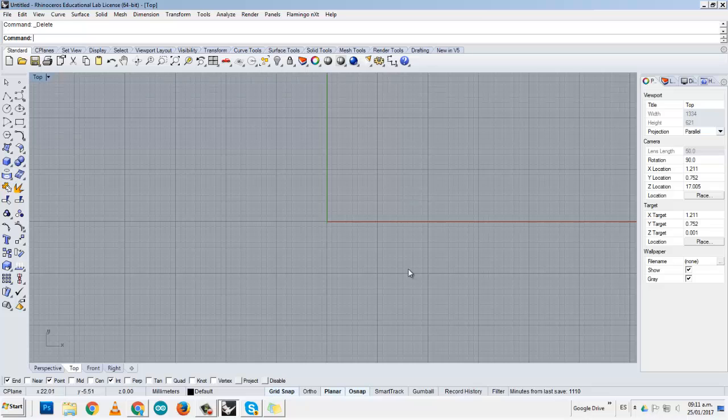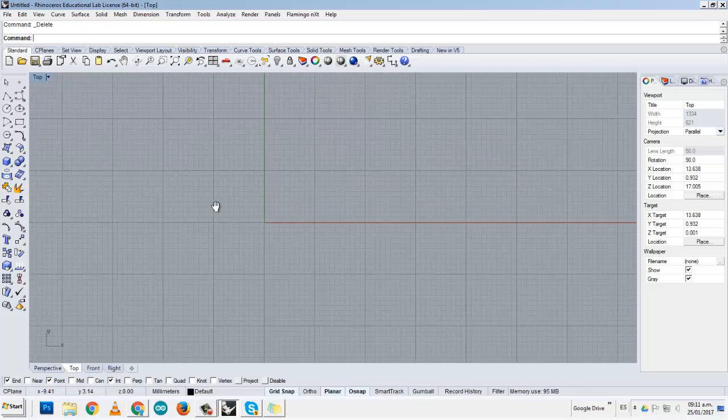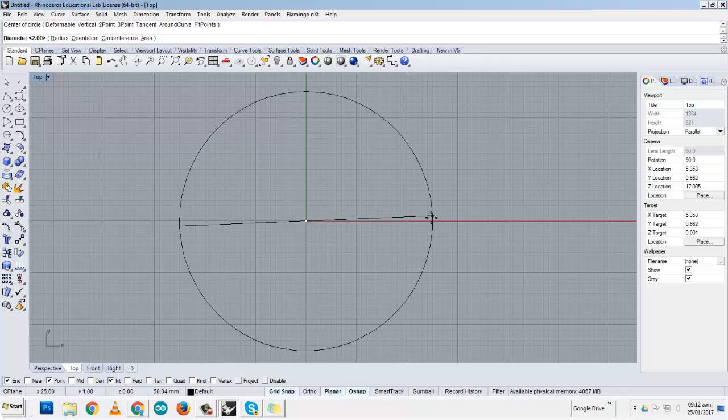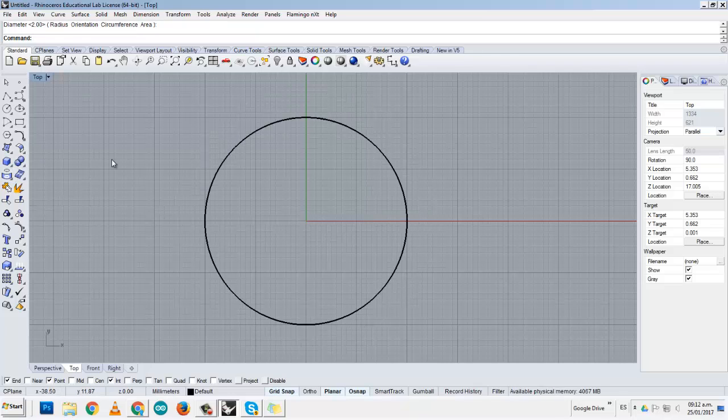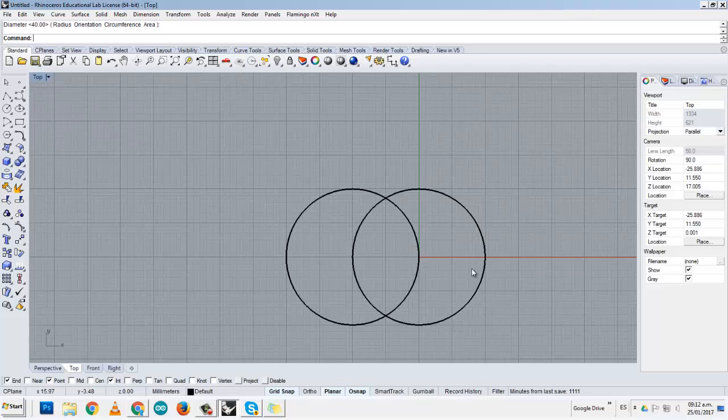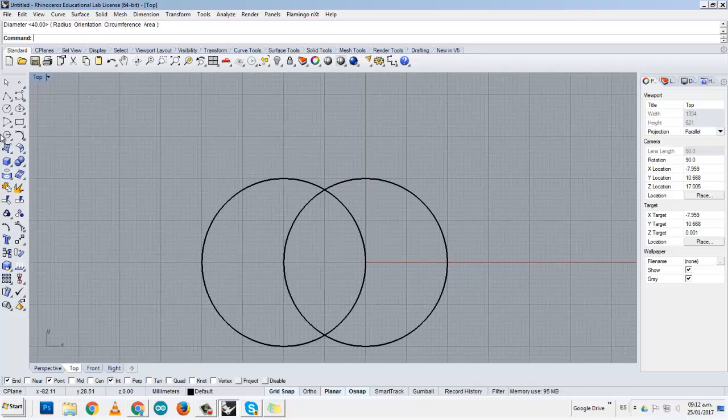Well, basically, you don't have to do this. You just have to pay attention until we actually start developing our project. So Boolean curves is basically taking out the region or the regions that you need from the intersection of two curves. So I'm going to make two circles, any size, and I'm going to intersect them. Okay. As a matter of fact, I'm going to get 3 circles,